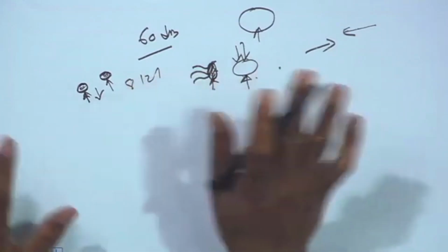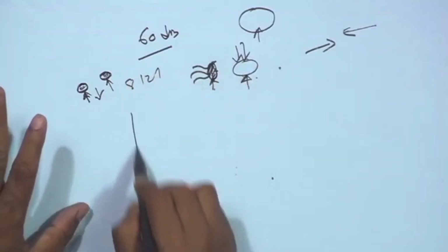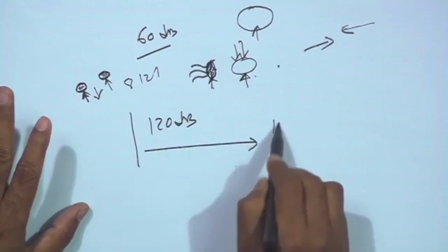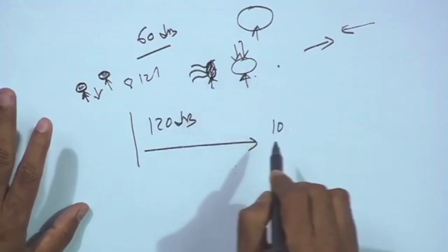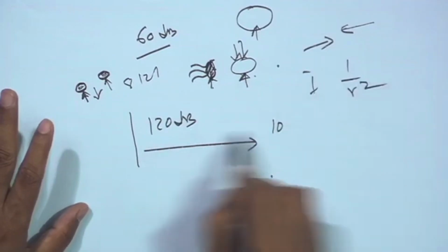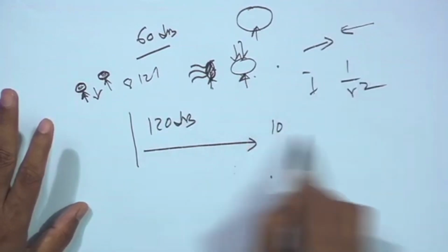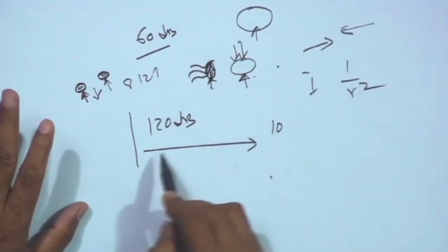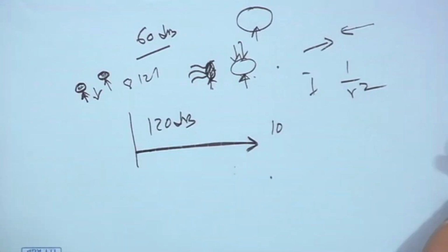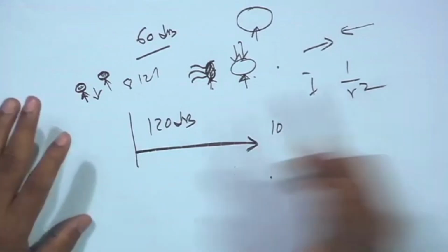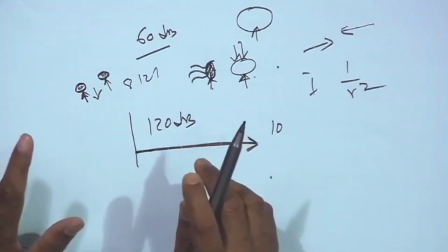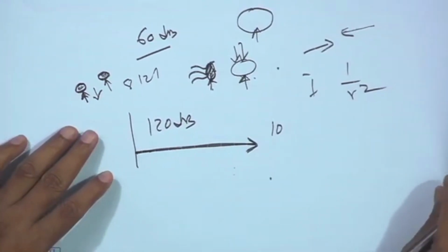So, there is sound propagation, you know that even if a source produces 120 dB, if you are 10 feet away, then you know the 1 by r square. So, I is reduced in 1 by r square form. So, with every doubling of the distance, the level goes down by 6 dB. So, 10 feet away from the source, it will reduce the sound intensity, but do not always expose yourself to a large sound, so that your ear sensitivity is lost.